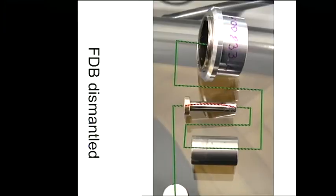This is a fluid dynamic bearing from the inside. I would say 99% of all hard drives are using fluid dynamic bearings in the spindle because ball bearings and other types introduce too much noise into the mechanical system. And this is the bearing dismantled, and you can see the platter hub on top.